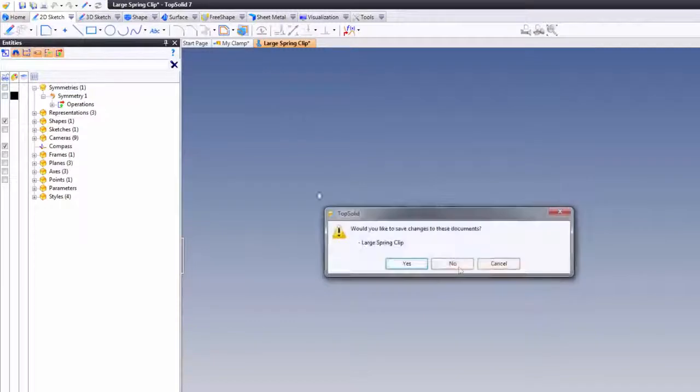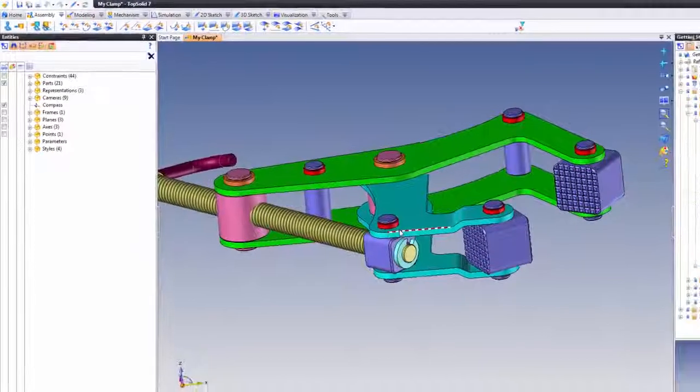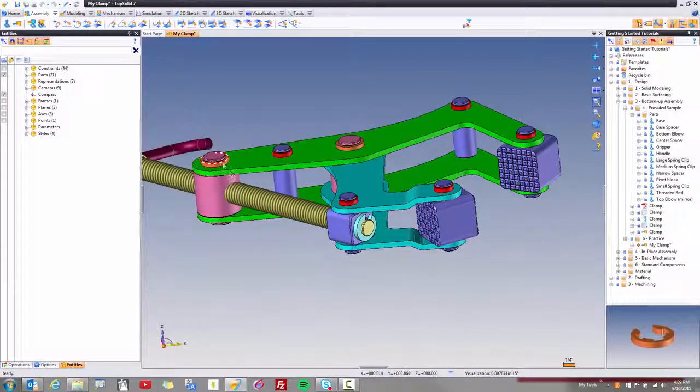Perfect. Why this is important: when we mirror these components in here, TopSolid knows that it's okay to mirror about a plane parallel with the plane described in the part. And if this happens, it's okay to allow the symmetric repetition to happen. Otherwise, if we mirror about a different plane or axis, the software will assume it's a non-symmetric part, and it will automatically derive a mirrored version.